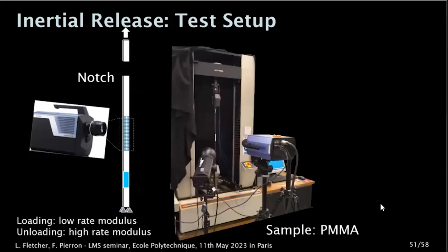So this is the experimental setup. One of the tricks is the triggering, of course. You can post-trigger the camera, that's easy, but you can't post-trigger the lighting. Because we don't know when it's going to happen, and we only know when the break happens, we have to have a specimen that is long enough so that the wave traveling down to the field of view is on the order of the rise time of the flash. So that's a slight downside.